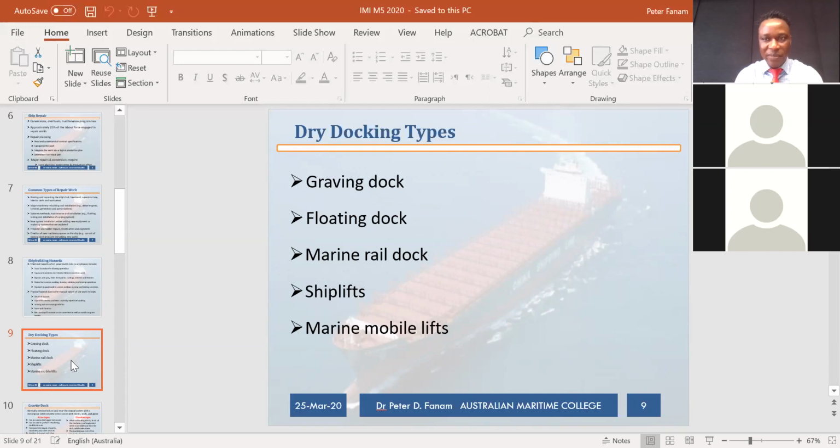Yeah, so a dry dock is where a ship is completely taken out of the water and put on a dry dock, where the ship is completely out of the water. As you rightly point out, the dock will be flooded with water so that the ship has access to come to that place, and then the water is pumped out of the dock, and the ship will be left on dry land so that the maintenance work can be done on it. So yeah, that is correct.